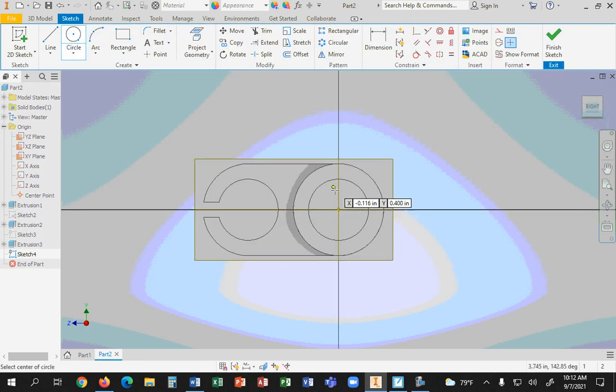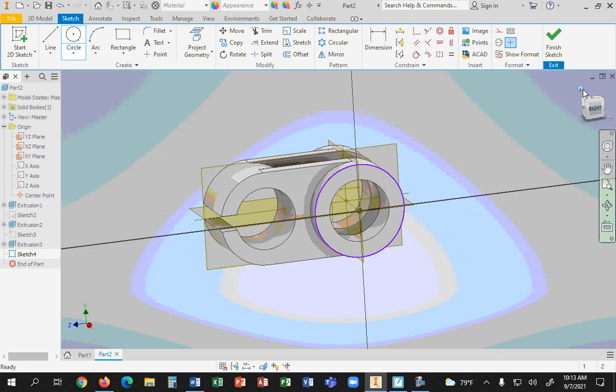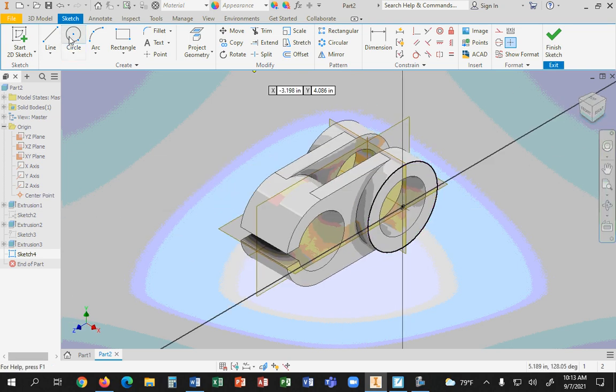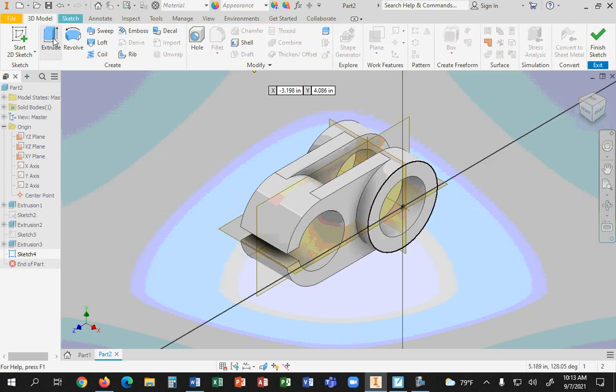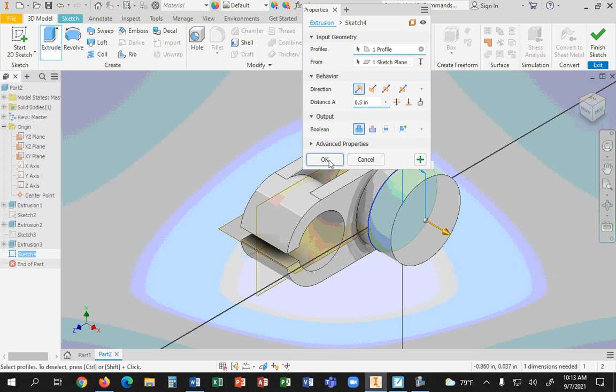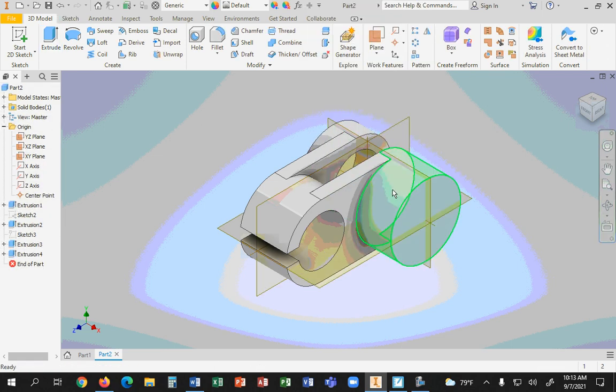When you draw that second circle, touch the other object, because when you do that, it confines it to that object. So they literally share the same shape, the same diameter, radius, whatever you want to call it. Then when you extrude that object,